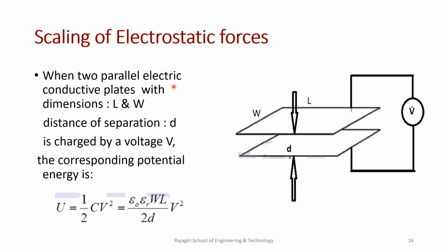The mathematical expressions for electrostatic forces have been discussed in Module 2 of this course. Here we will revisit the configuration of a parallel plate capacitor in order to discuss the scaling of the electrostatic forces along with the scaling in the dimensions. In the parallel plates shown in this figure, W and L are the width and length of the parallel plates respectively. D is the distance of separation between the plates.